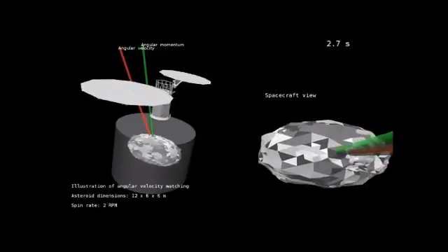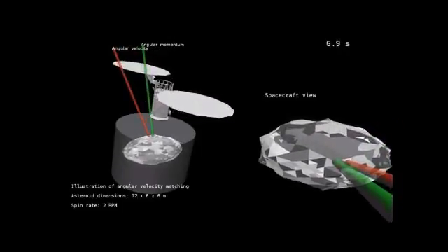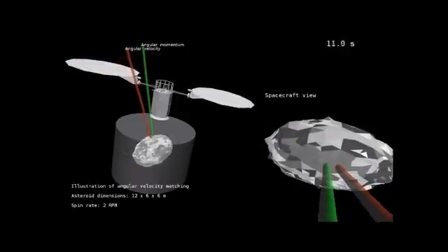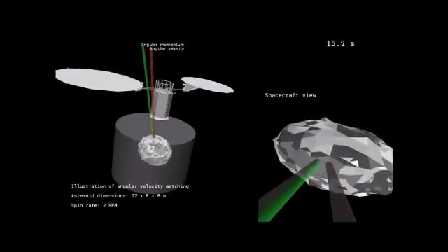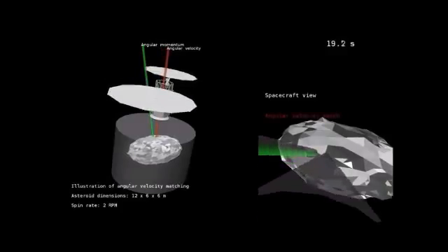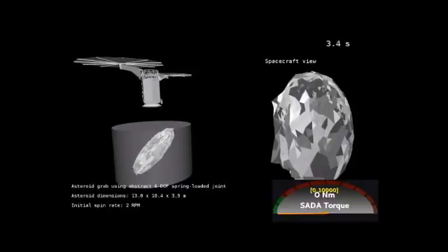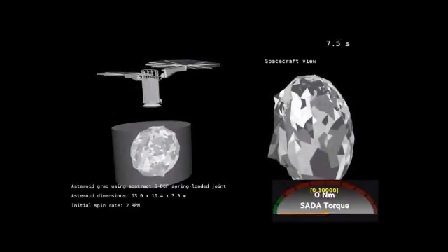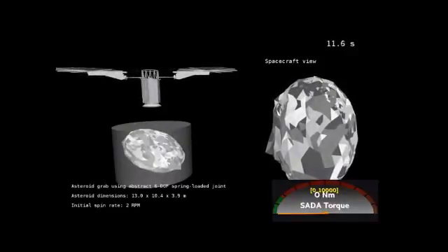Now here we have lined up the spacecraft on a future spin state of the asteroid, where at 30 seconds it will map exactly onto the instantaneous spin axis. So as the red axis approaches the line of sight, that's when there's no apparent motion, no motion at all for that brief instant. And so if you take that approach, that's the approach that we prefer for the faster spinners.